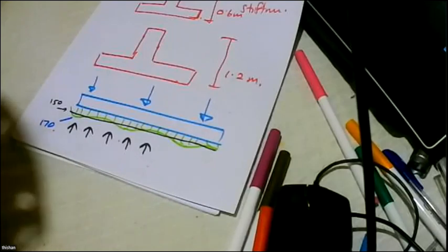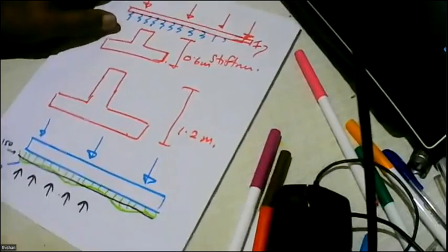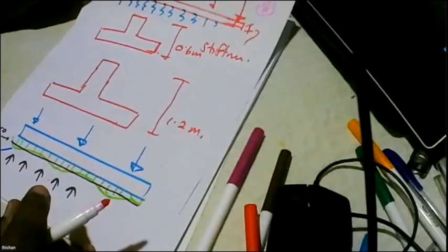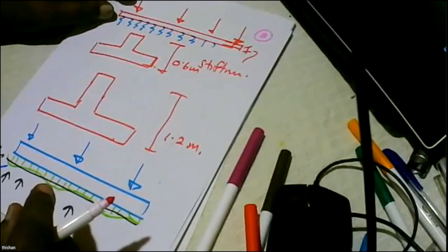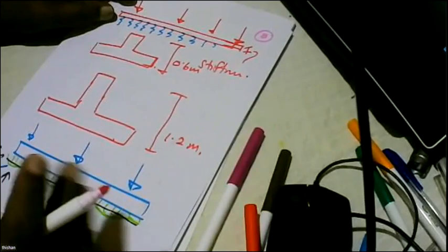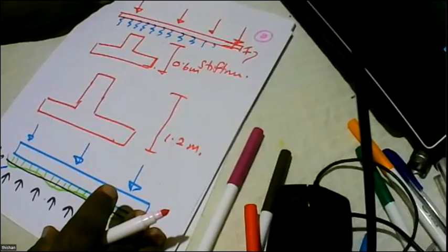So it's all up to you. But with these Winkler springs, we are providing you with a tool to do experiments in a very short time, because it will not take a lot of time to do these experiments, because once you make the model, you can change the shape of the beam. The depth of the beam can be easily changed within 1 or 2 minutes. You can do it, rerun it, look at the results, and you can have a lot of interesting experiments before we select the actual parameters for the building or the bridge